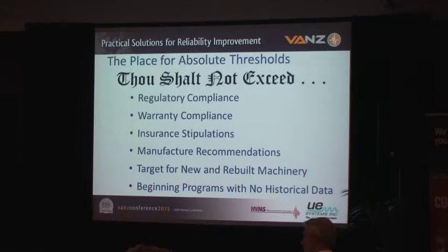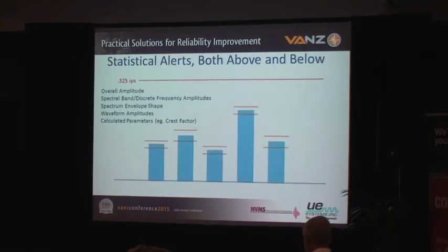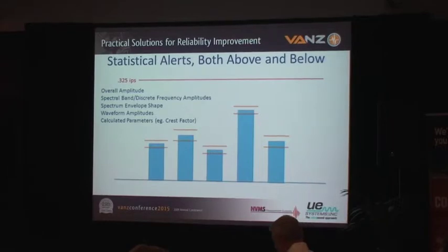I think the ISO amplitudes give you a really good starting point, but I firmly believe they should only be treated as starting points. Because if we took a look at the statistics, for example, on those 5 general service water pumps that I talked about earlier, what you would see is, in all cases, they were well below the,